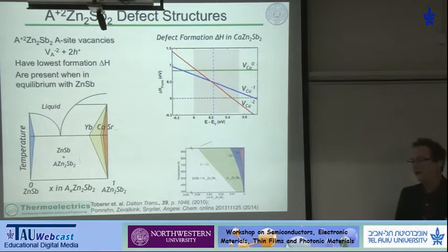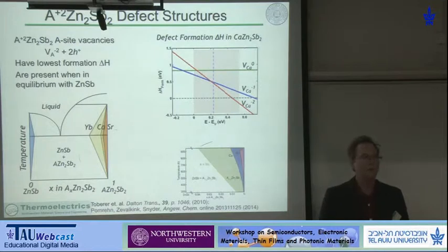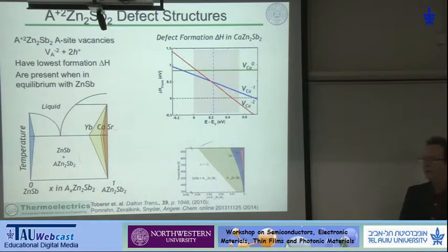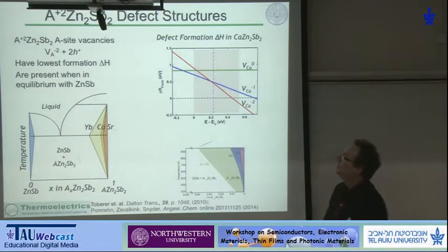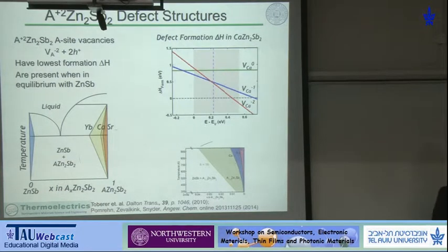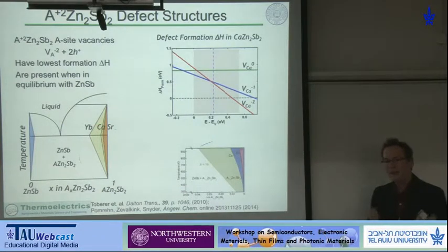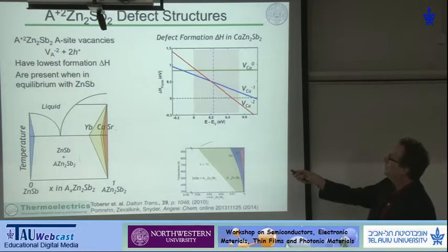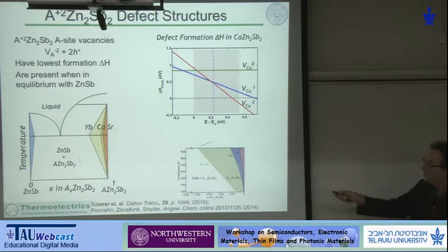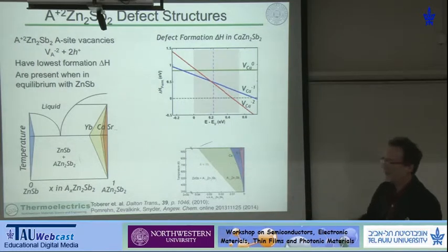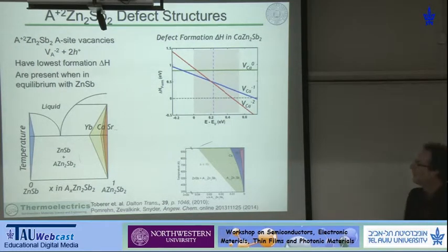Okay, so with that understanding that these defects are actually equilibrium controlled, that the defects can be calculated from first principles, we can go back to our structure and propose that this ytterbium vacancy has a bit of chemistry to it, and we can calculate that, for example, the calcium version or the europium or the strontium will have slightly different vacancy energies, and then calculate this phase width for the different materials.